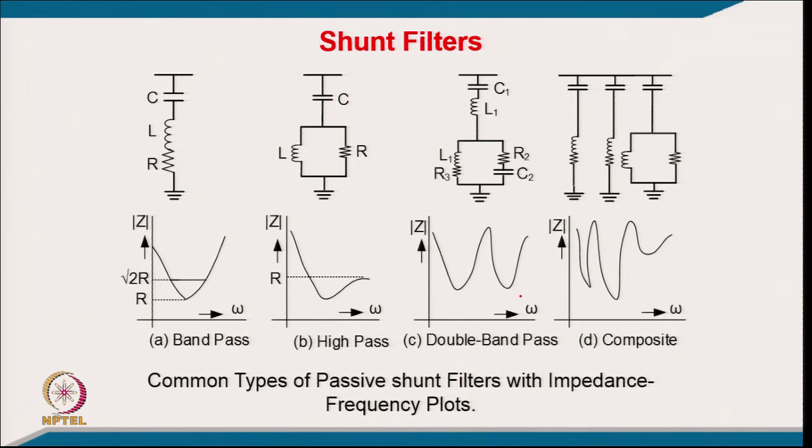So, it is tuned corresponding to two frequencies, maybe fifth and seventh for 3 phase. These are the two dominant harmonics in 3 phase, or typically for single phase, the third and fifth harmonics. So, these are dominant harmonics, you can tune corresponding to that, to take care of both harmonics by one circuit itself.